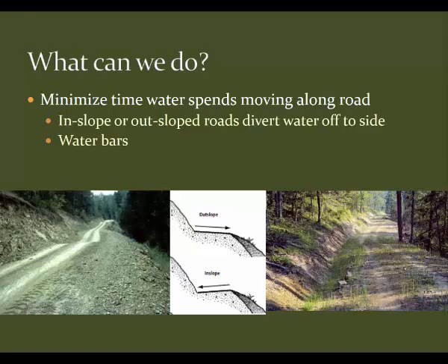Other things that we do are water bars, basically where we build little bumps in the road that, again, would prevent water from running down the grade of the road and hopefully direct it off to one side or the other.